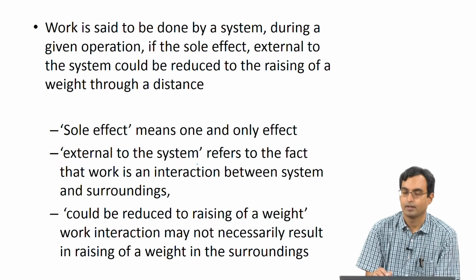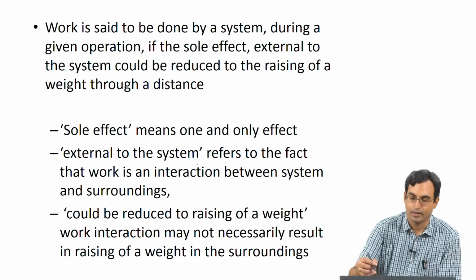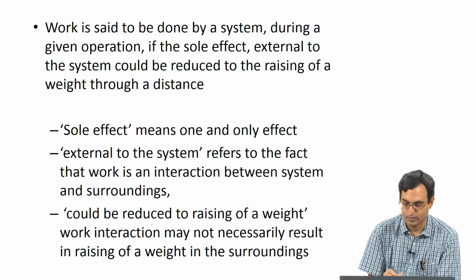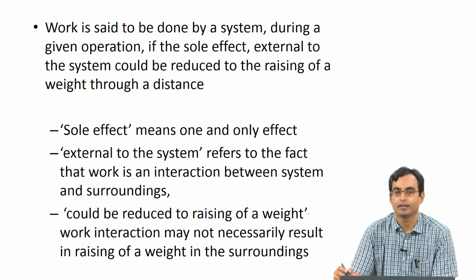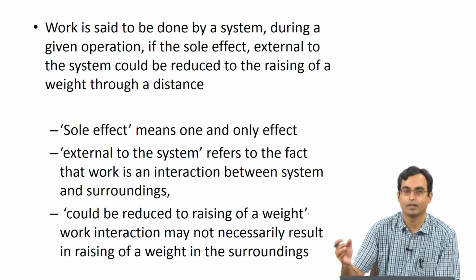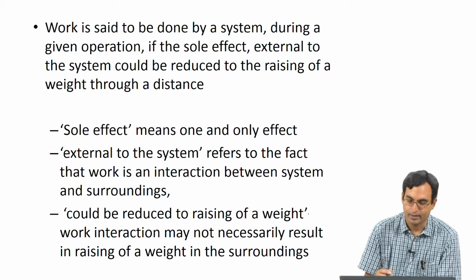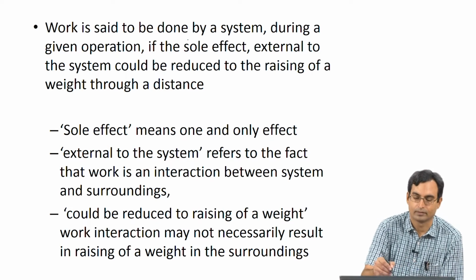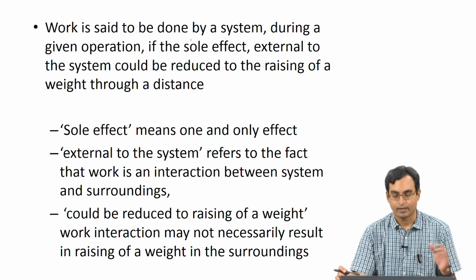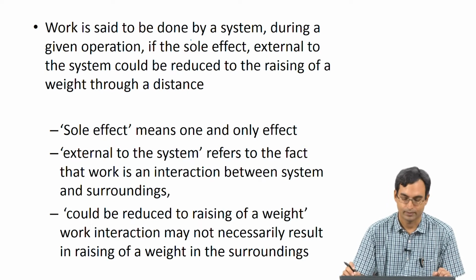So, that is what we mean by external to the system. This emphasizes that work is an interaction between the system and the surroundings. We say work is done by the system if the sole effect external to the system could be reduced to the raising of a weight. It means that there does not actually have to be a weight which is raised, but if whatever is being done by the system on its surroundings can be thought of as raising a weight, then we say that work is done. That is essentially what we mean by work. You might want to pause here and go through the definition again and see if you have understood it before going ahead.